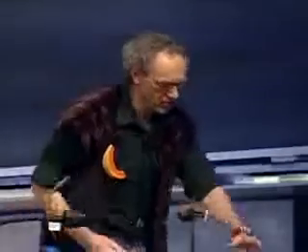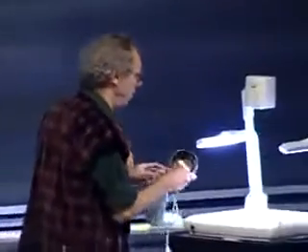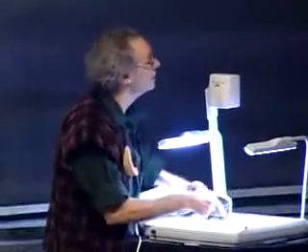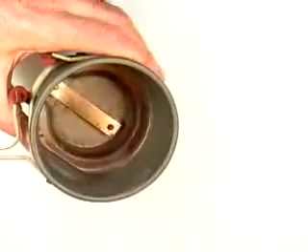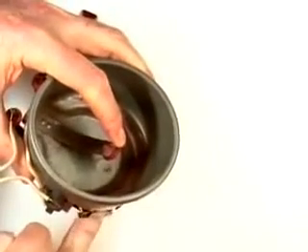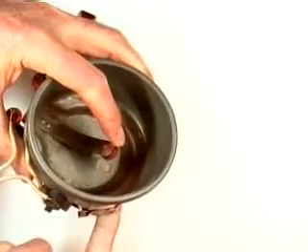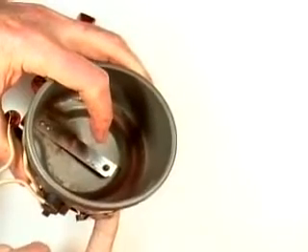Here is that coffee machine. It's not working anymore. It's a very old one. But I want to show you at least that bimetal. This is that bimetal strip. Water goes in here, you heat it, and when it's hot enough, the bimetal lifts up, and you can see there is a hole there. This is the hole. And the water comes out, and when the bimetal is closed, then it closes off that hole.